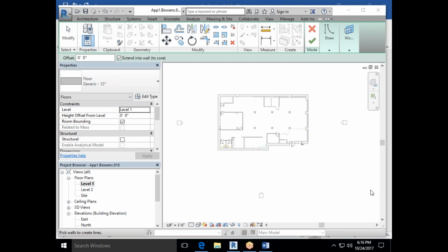Types. So that's just at the point of creation, like when we're in this draw mode, under the properties selector, you select the type before you finish. Although after the fact, if you do create a fill pattern that you can select the boundary for it, then you can click on it and it'll highlight that, and then over in the type properties you can drop the arrow down and select it after the fact and change it later on.